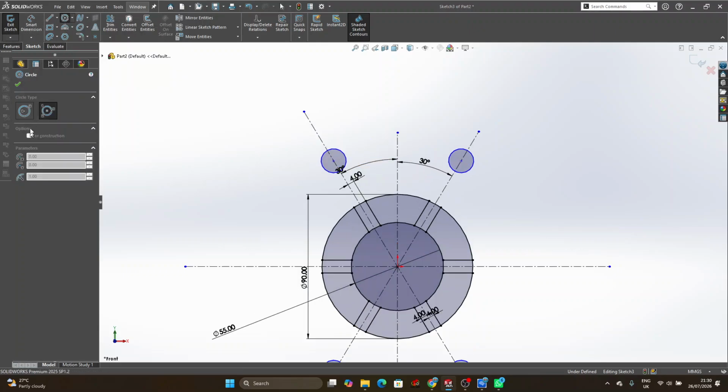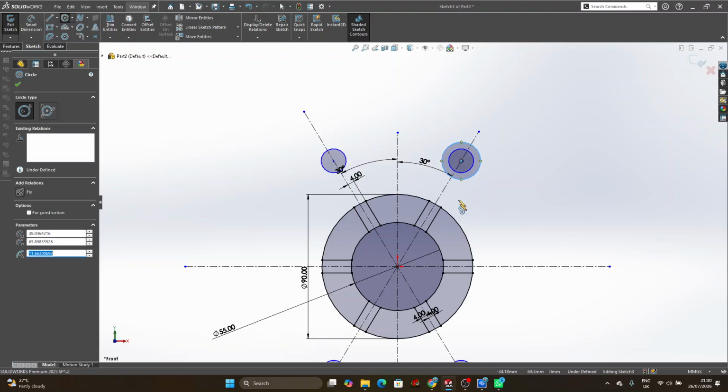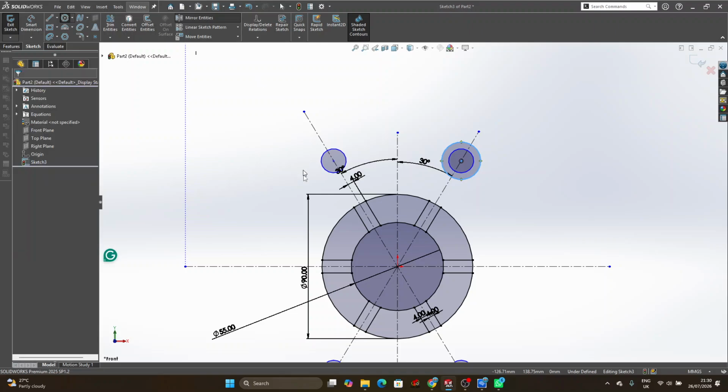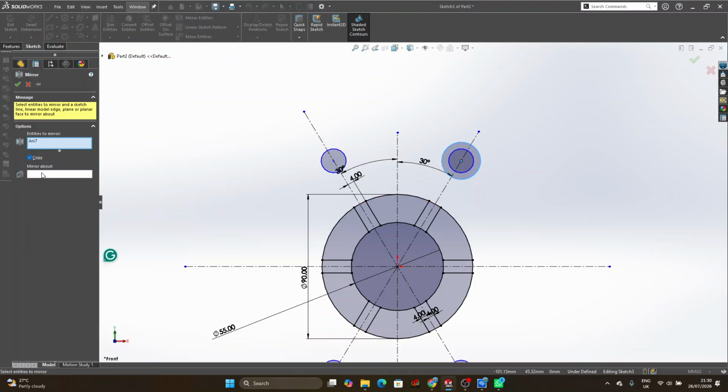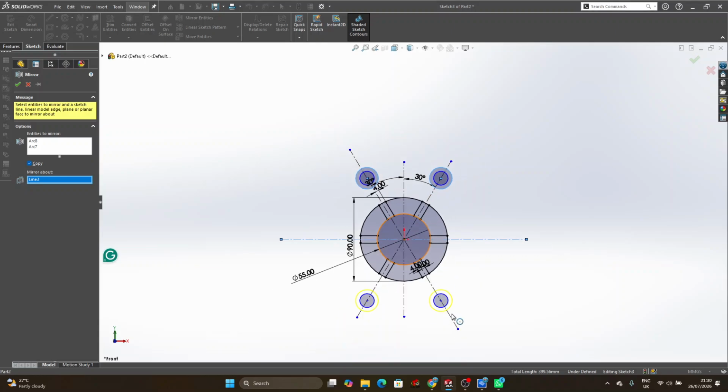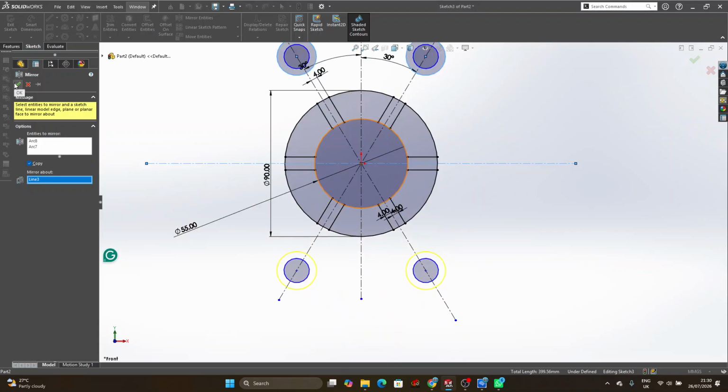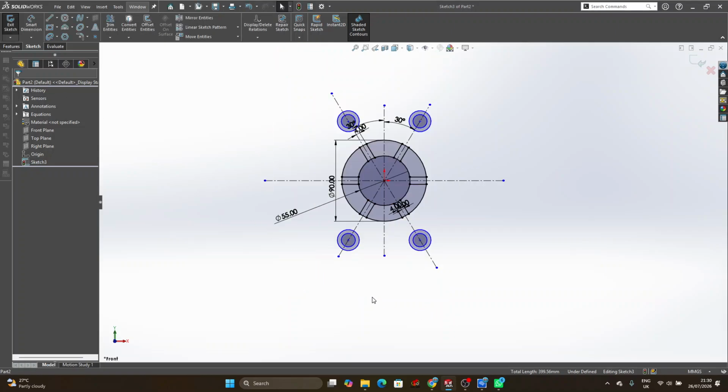So normally I made a mistake. I should have drawn the second circle too and mirrored it too. So I would have mirrored the two together, instead of wasting my time. So that's a mistake on my part. So I have to mirror this one too. Mirroring about here. So I'm clicking on the mirror entity tool again, mirroring it about here. Done. So I've successfully mirrored it now.